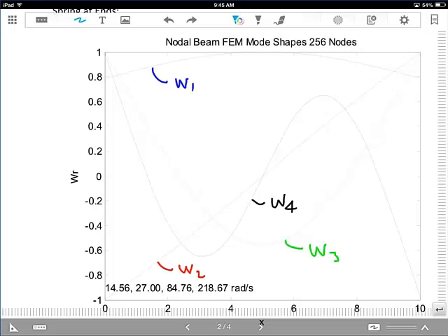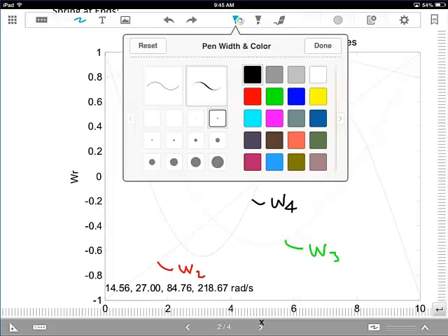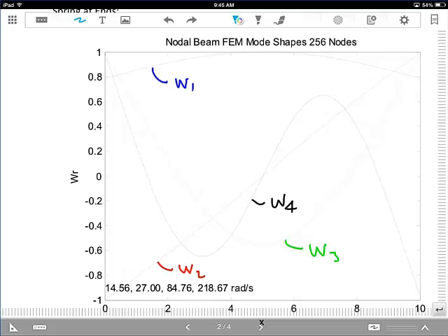So these modes look pretty reasonable. They should be symmetric. So you can see, for example, W2 is going from -1 to +1. And that makes sense. You have this rocking mode where the whole beam is rocking back and forth, sort of like a rigid body. Omega 1 is the whole beam bouncing up and down. You can see the springs are having some impact because it's not a straight line anymore.